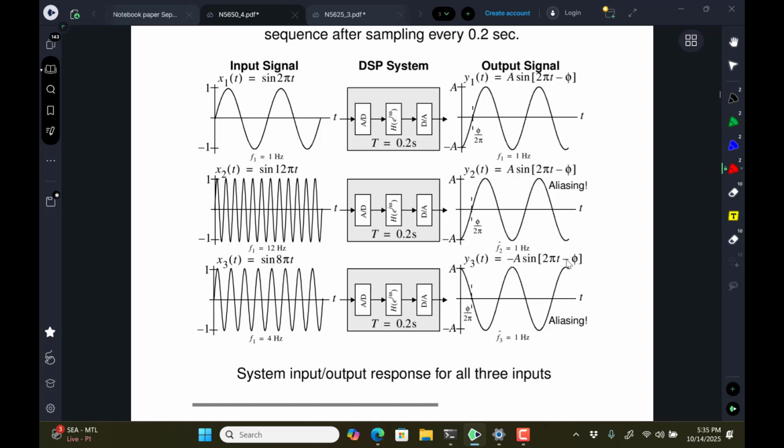So if you don't have any protection in front of the A to D, it just lets anything pass, ideally at least, and aliasing occurs, so all of those look very similar to each other. In the lab, this isn't possible to do with our current hardware in the DSP lab, but in the beginning, when I was teaching with different hardware, I had an Arduino that I used with an A to D and D to A that did not have either the anti-aliasing filter or the reconstruction filter. It just gives you a flavor for what things are doing.